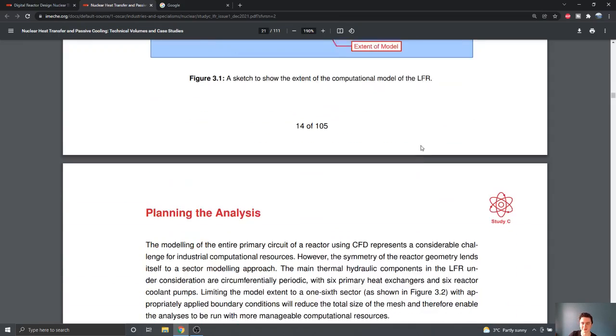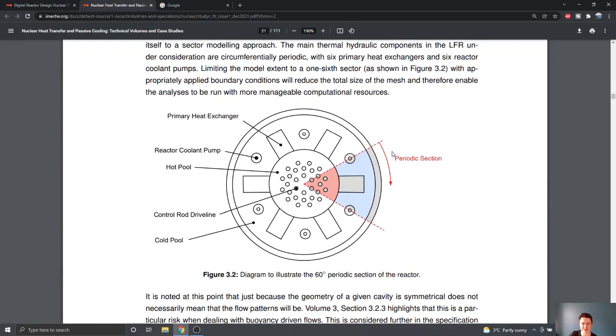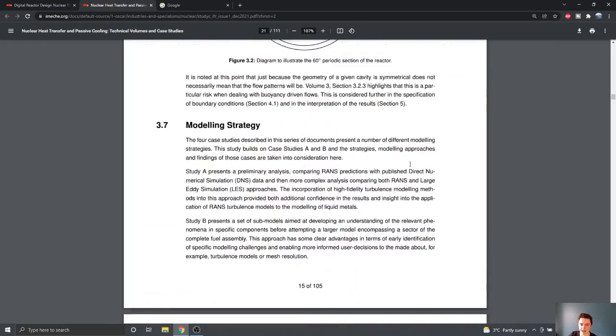So those are the first 2 simplifications we can make when modelling this reactor, and it's very useful in all of your CFD analyses as well to take some time to think about what the extent of my domain is, how far does it truly extend, and can I do anything clever with symmetry boundaries or periodic boundaries when I'm analysing my model.